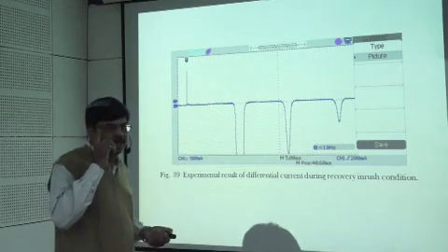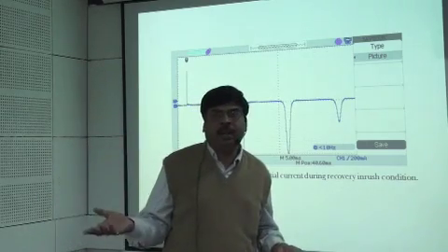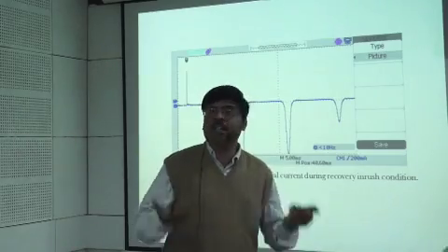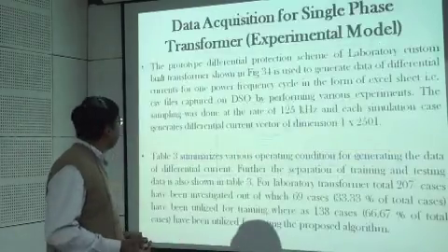Waveform during recovery inrush means I have cleared the external fault, and as soon as the external fault is removed, the voltage is increased and an inrush is observed, called the recovery inrush.